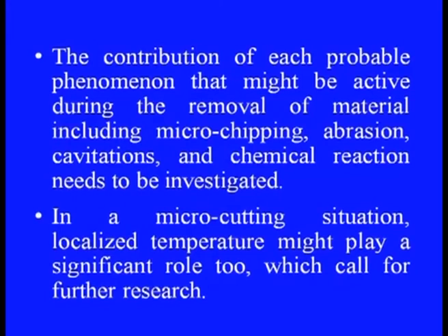Another point could be further analysis of the material removal mechanisms associated with the machining process that needs to be addressed. The contribution of each probable phenomenon that might be active during the removal of material, including micro chipping, abrasion, cavitation and chemical reaction, needs to be investigated. In a micro cutting situation, localized temperature might play a significant role too. Therefore, this needs to be evaluated.